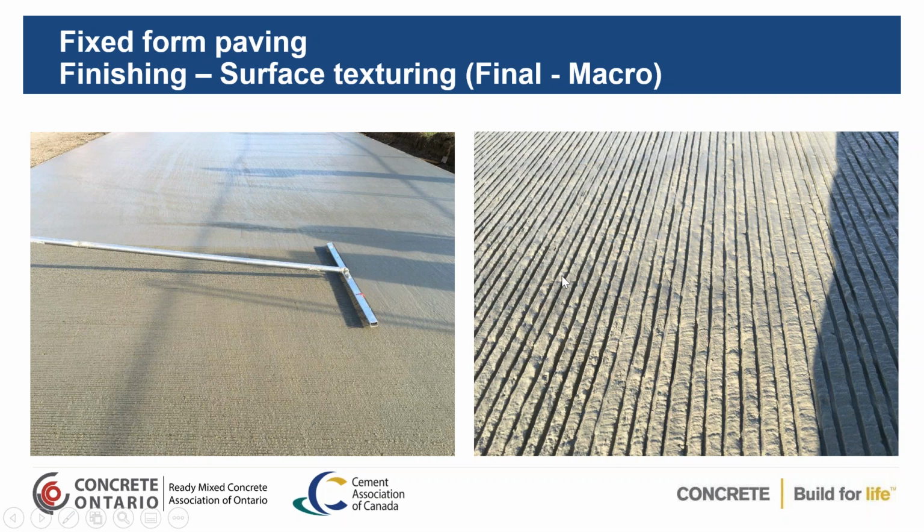The deeper these grooves, the louder your pavement. So you want to stay within specs. Deeper is not better. Stay within the specs itself. It can't be too shallow because it will wear off over time, but it can't be too deep because that'll increase your noise level.